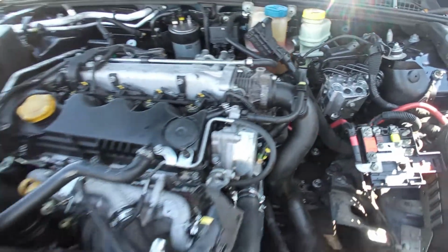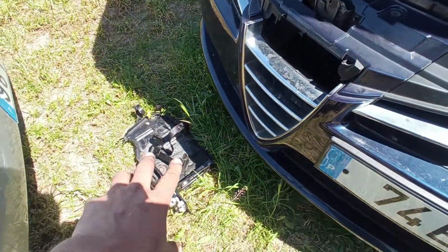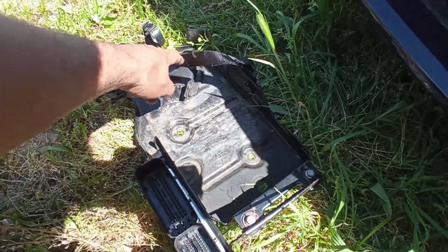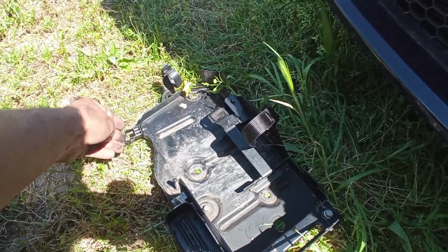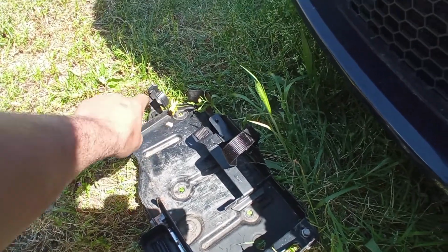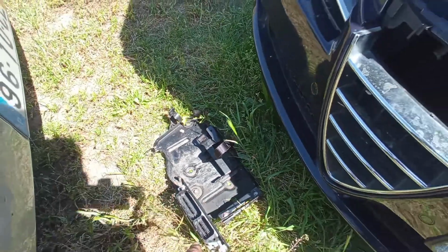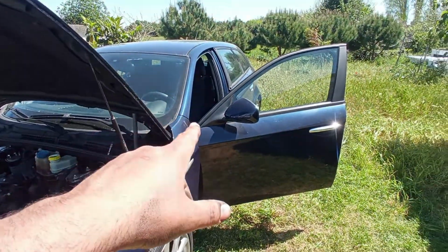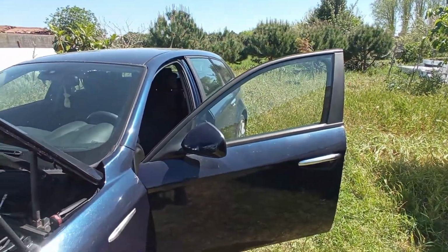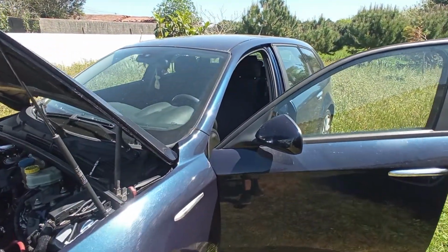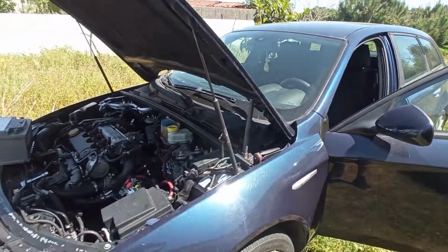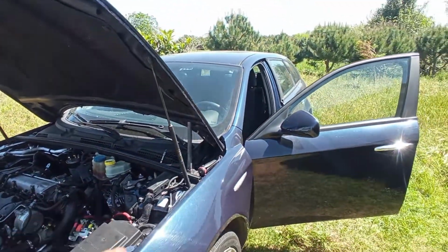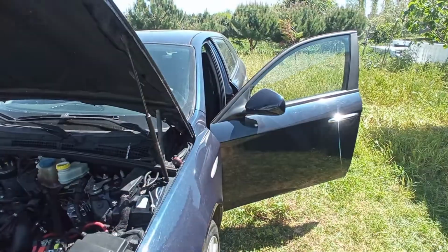And now just put in the battery tray. Make sure to put the 3 bolts on, 1, 2, 3, and all the clips for the positive cable, for the harness of the ABS, and the harness for the control unit for the engine. Meanwhile, you want to have at least one door open, because if you have your key inside, the central lock when connecting the battery can act up and lock your car, leaving you stranded. So always leave a door open for that.